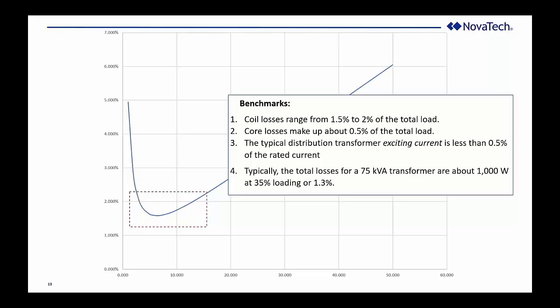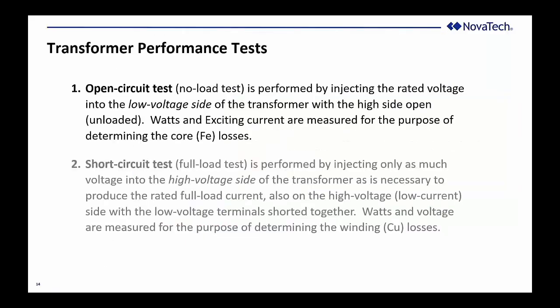And that's the important part, the measurement of power on the opposite side of the transformer from where the meter is connected. So everybody has to start with the nameplate that is provided by the manufacturer of the transformer. The nameplate characterizes the performance of the transformer based on tests that are performed after the transformer's been manufactured and before it ships.